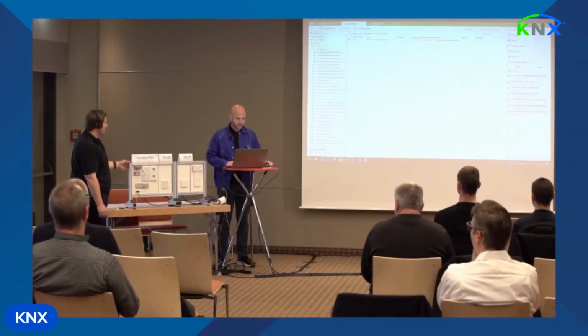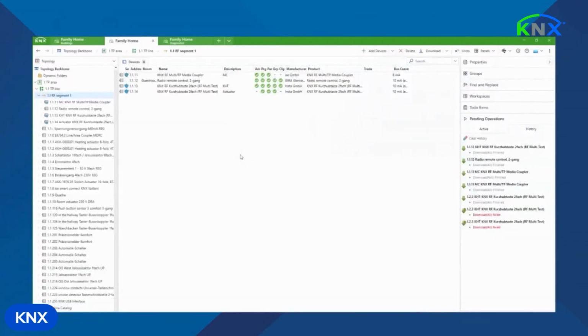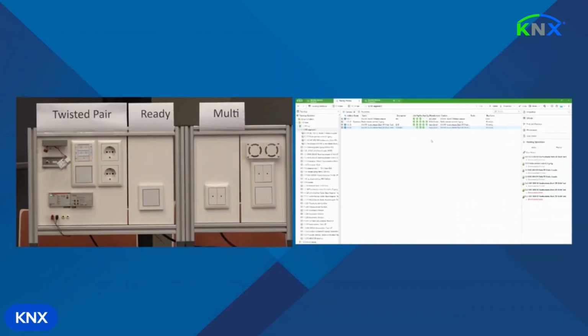It will have security activated as it's a KNX RF Multi device, for the protection of the commissioning. But also what we want to see now is the runtime communication. So we need new group addresses on the push button and also the same group addresses on the actuator. Group addresses in the new UX of ETS 6.1 you will find in the sidebar conveniently. And oh, here's the desk light. Yes, use this one. How convenient.